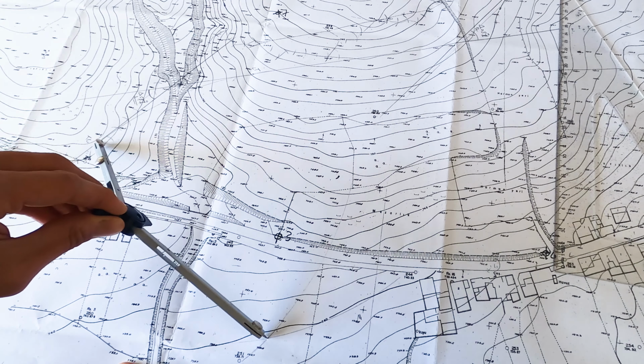Because the first and the second have the same details, we can take the same semi-tangent distance, which is 8.4. So approximately this is 8.4 from the intersection point on the tangent.